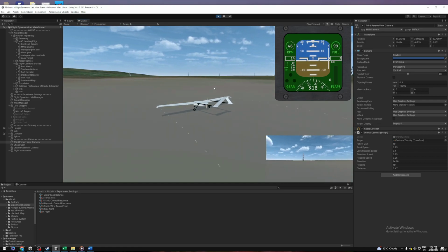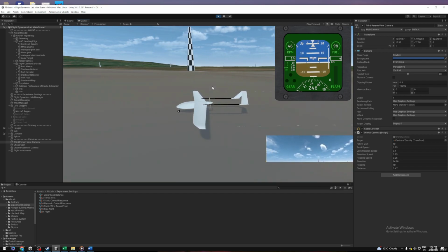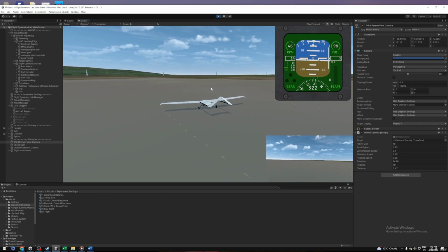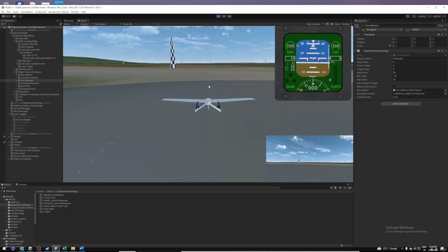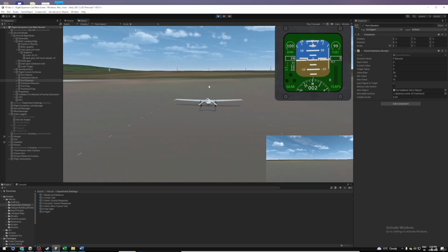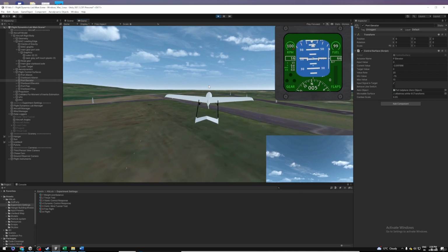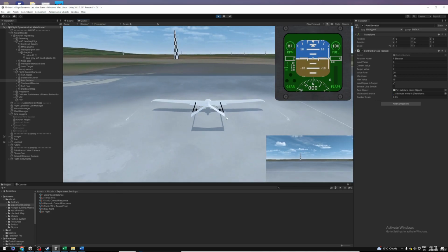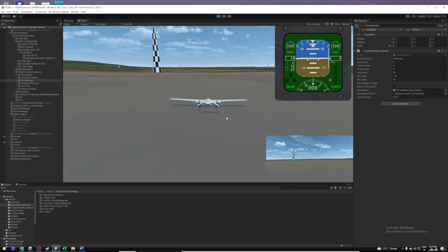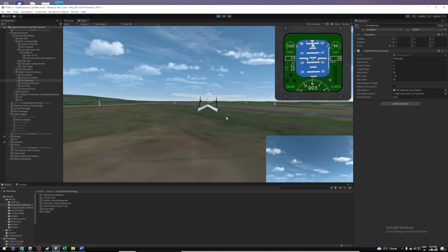Before going into free flight, we use a center of gravity position within the suggested range and perform a ground maneuvering and taxi test. The goal of this test was to make sure the pilot had enough control when handling the aircraft on the ground while taxiing. So the minimum speed required to fly the wheels off the ground without flaps is approximately 27 meters per second, as you can see. And with the flaps deployed, the speed decreases to about 25 meters per second. Notably, this is a significantly higher number than the estimated stall speed by around a factor of 3.